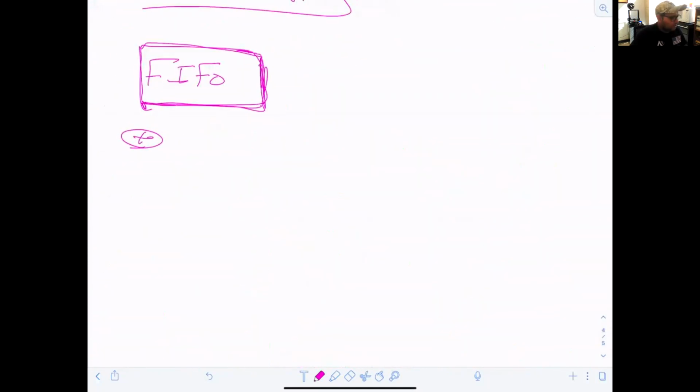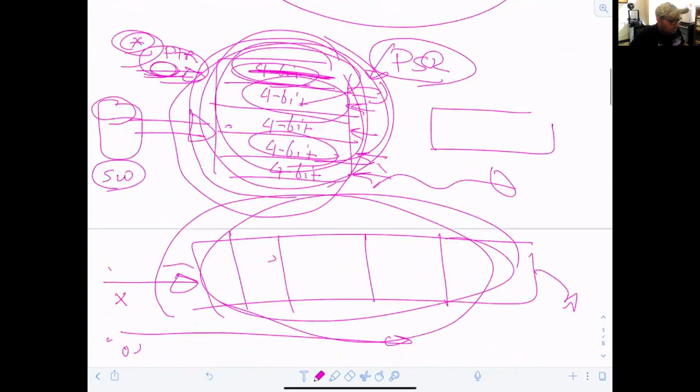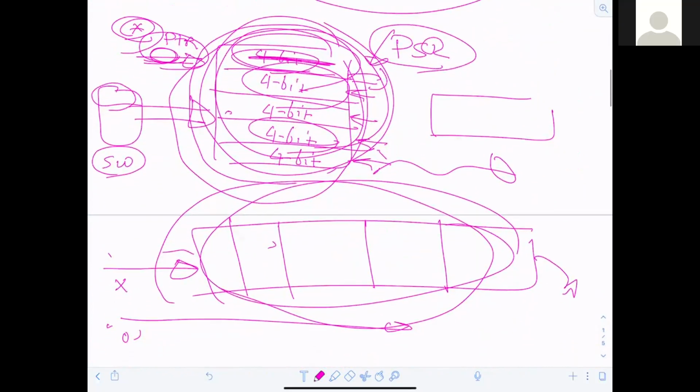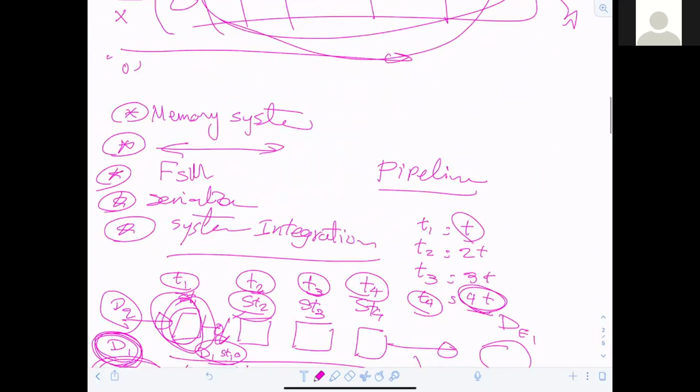You said you have another question. What was the second question? Can the output flag of the sequence detector be reset by anything else, like an enable or a disable switch, like a universal one? Yeah, you should have a master reset, right? Correct. You should have a master reset that when you click on it, everything will be reset.